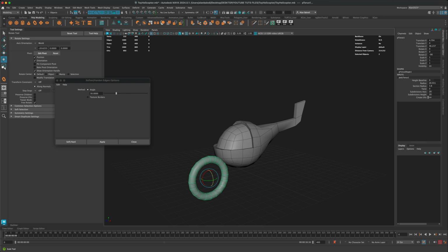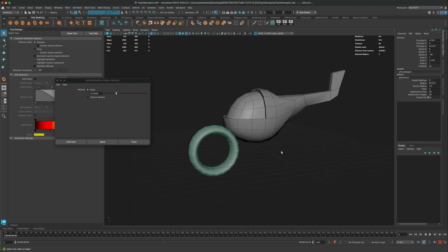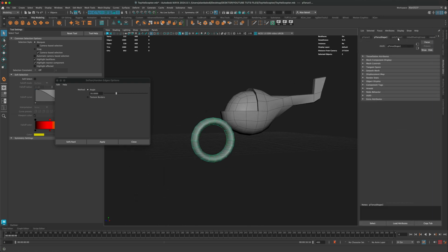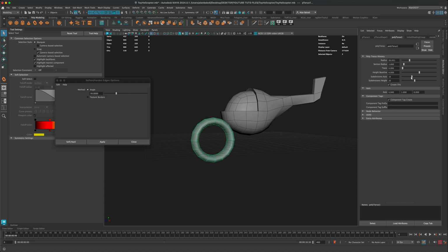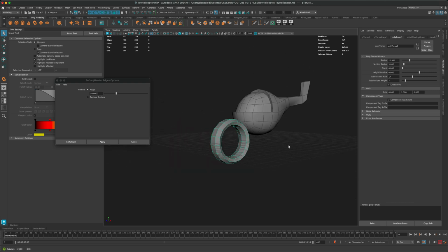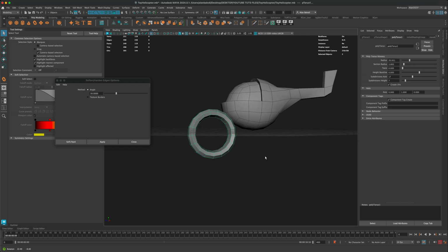All right. I'm gonna make this kind of wide. And maybe also let's go to attribute editor, and maybe let's turn off the subdivision for the height. I don't really need it to be that dense because I am building kind of a low poly model here.